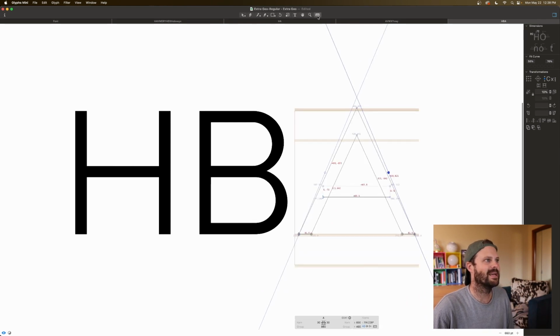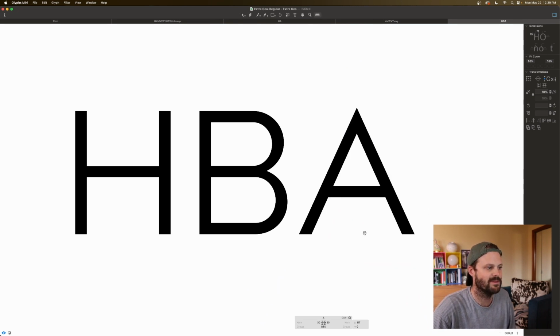And then I want to do the same thing, get my measurement tool and make sure, oh, you can see now that this is now 78 pixels wide, too wide, whereas this is 76. So I want to compensate for that, clicking that point, bringing it up a hair, and then I'm just going to switch between my measurement tool. Okay, 43 pixels. I believe we were at 44 before. So switching back and forth. Okay, 44 pixels, that works for me here. 76 pixels, I might want to bring that out just a hair. Measure it again. 78 pixels works for me.